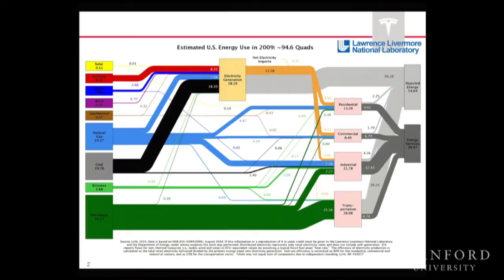The other story in this chart is about how efficient these processes are, right? So you look at the backside of this. Now they've just made an assumption down here about the efficiencies of various processes, so there probably ought to be error bars around all these things. This chart assumes that the fuel use in transportation is 25% efficient. I think that sounds like a good number. Every time I've gone out and looked, those are the kinds of numbers you see. It's hard to do better than that because there are so many constraints on an engine in a car, right? It has to fit into a certain volume, a certain weight, and a certain cost in order for it to work as a prime mover for a vehicle. Efficiency is only one piece of that total puzzle, right?